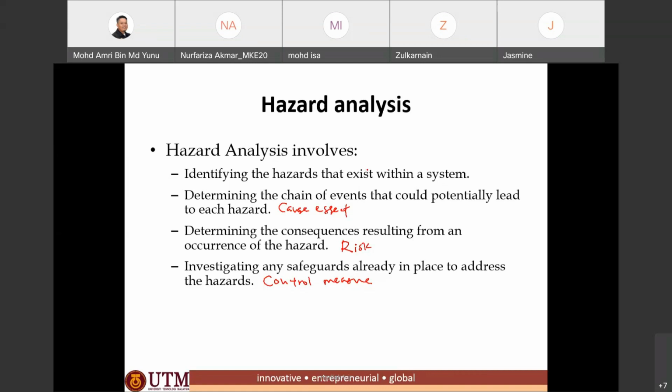So what will cause the valve failure, for example? If a valve failure happens, what should we do? One option is to install a safety instrumented system. We will look into that later. But now you need to know how to identify the hazards in your system itself. Your system may have moving parts, and the moving parts have limits, so you have to identify them.